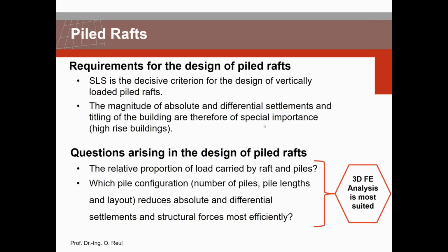In terms of requirements for the design of pile raft, the serviceability limit state is a decisive criterion for the design of vertically loaded pile rafts. The magnitude of absolute and differential settlements and tilting of the building are therefore of special importance, especially for high-rise buildings. The questions arising in the design of pile raft are the relative proportion of load carried by raft and piles, and which pile configuration, in terms of number of piles, lengths and layout, reduces absolute and differential settlements and structural forces most efficiently.